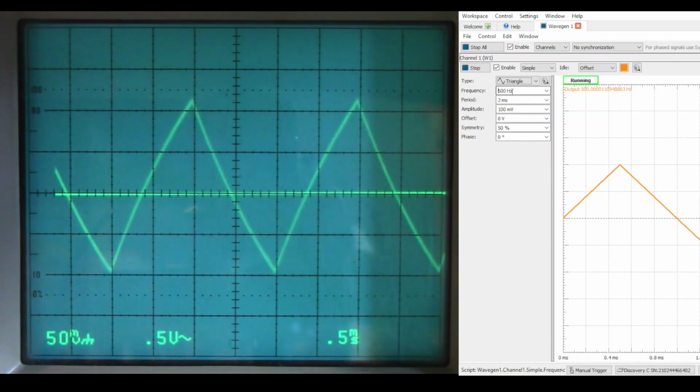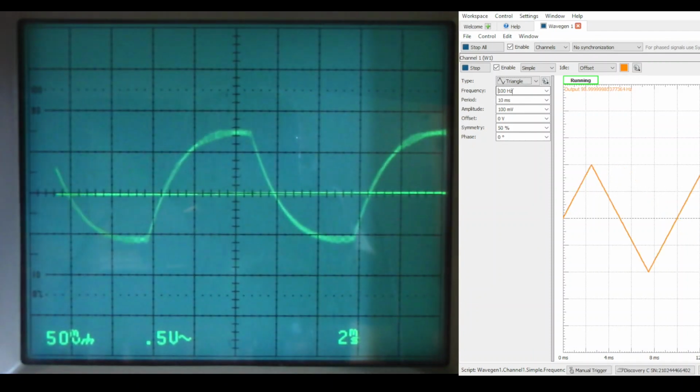And you can see something's not right anymore. Those lines curved. And at 100, you can definitely see that something's wrong. You may recognize this as capacitors charging and discharging. Stated another way, this amplifier, as built, has a problem with low frequency response.